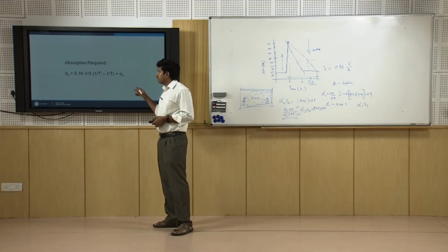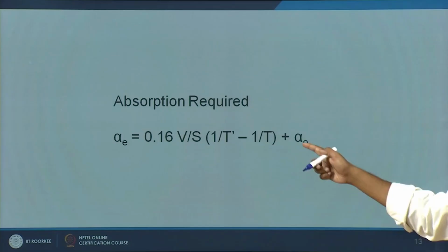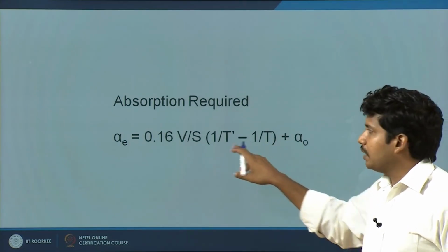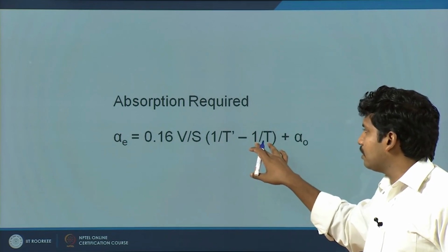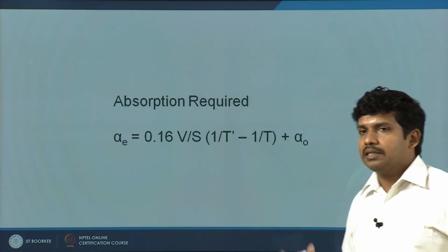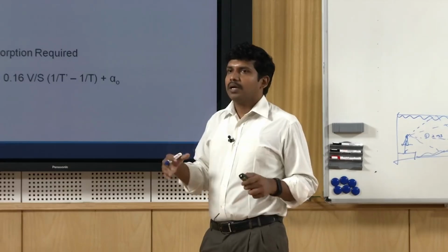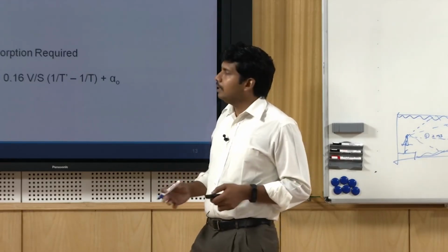With a simple reworking of the formula, you can actually find out what is the expected absorption. So if you have the required reverberation time and the actual reverberation time, you can find what is the expected absorption. This is a typical field problem. You already have a room in which you have to add absorption material. How much absorbing material will you add?